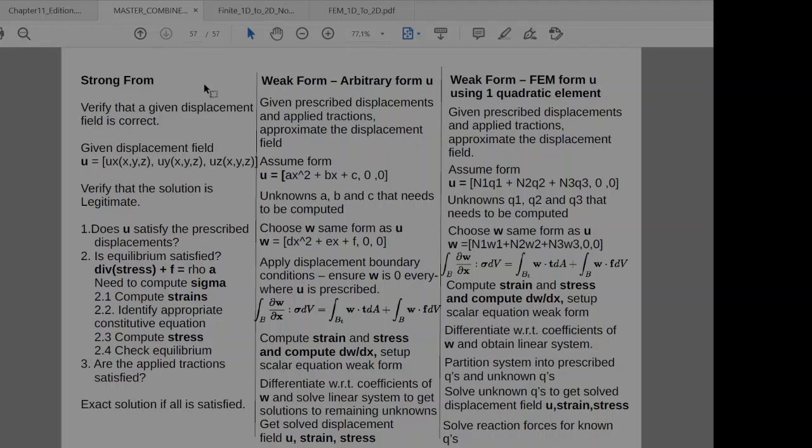And then we started developing the finite element method, where we brought in the idea of shape functions, N1, N2, N3. Their sum must be equal to 1 to make sure we can handle rigid body motion. There's a couple of characteristics. We constructed them in such a way that they are 1 at one node and 0 at all the other nodes, so that they have a very specific, nice meaning. And we learned about consistent nodal loading. We learned about body forces, displacements, understanding that displacements are enforced exactly, tractions are enforced approximately, and equilibrium is only satisfied approximately.